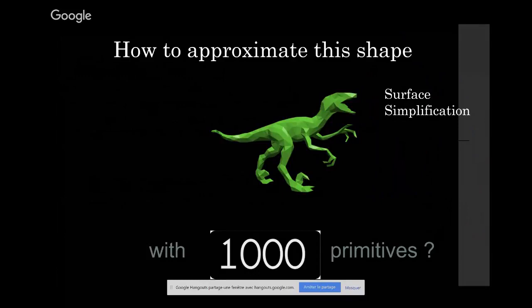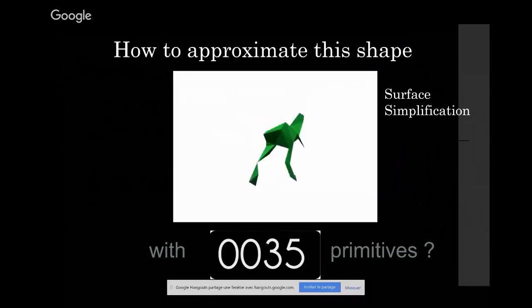This is here using the quadric edge collapse algorithm, the QSlim program, if you know it, by Garland and colleague from '97. Still really close to state-of-the-art today, very simple to use, and works pretty much all the time, unless you try to move to very few primitives. And at this point, you realize that with so few numbers to represent your approximation as a surface mesh, actually the simple fact to bound the volume of interest with a few triangles in space becomes too costly. You basically do not have enough numbers to properly reproduce, for instance, a proper topology for our shape here.